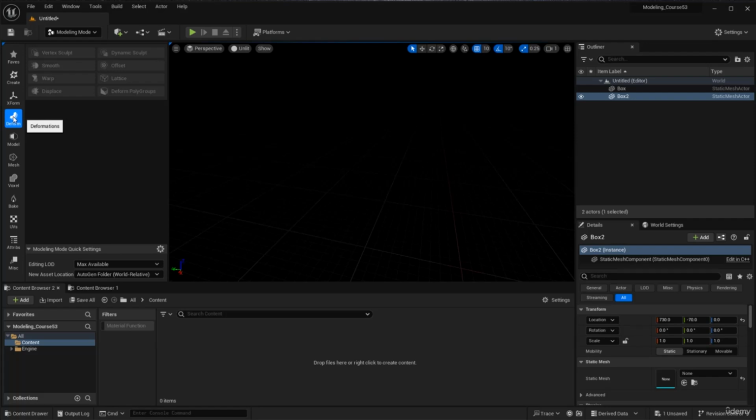We're gonna cover everything. Here you can edit the poly groups, like extruding multiple triangles together, applying Boolean operation on the mesh, like subtracting one mesh from another one. In the Mesh tab, you will find everything about editing the triangles, like selecting the vertices, faces, and edges. You can extrude the triangles, move them, weld, delete, flip, offset, and so on.